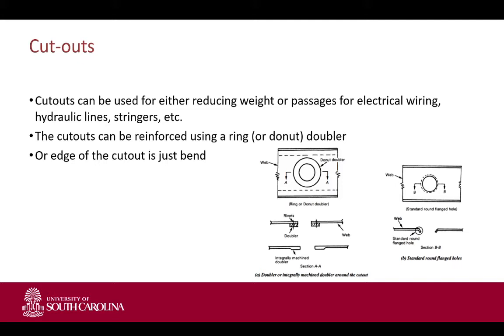But most commonly, regardless of what type of window or cutout you do, you have to reinforce it. You cannot just leave it open as is. Stress concentration will rise, so you have to take into account that the stress concentration will be high at those locations, and you have to come up with certain circular reinforcements to cope with the stresses in those cases.